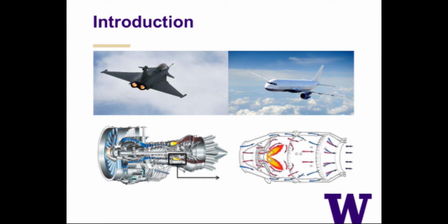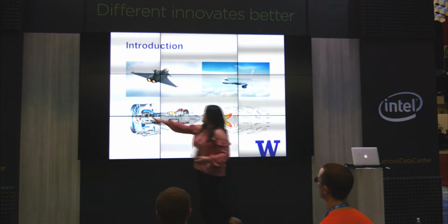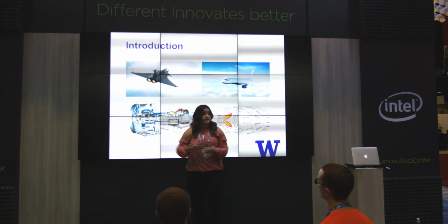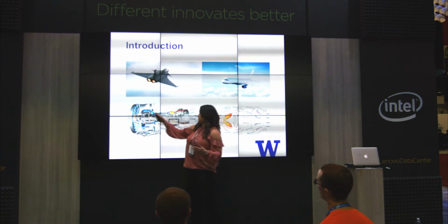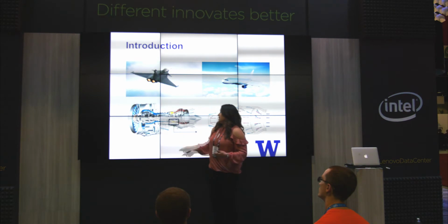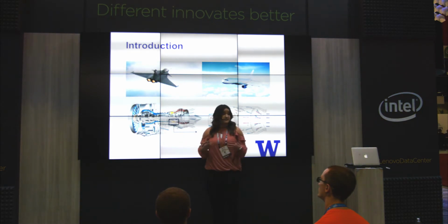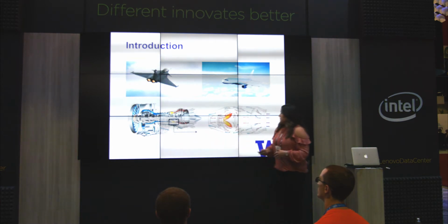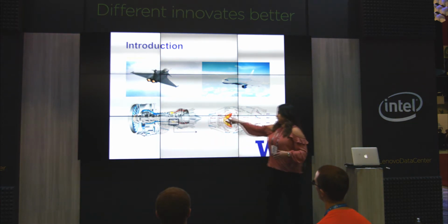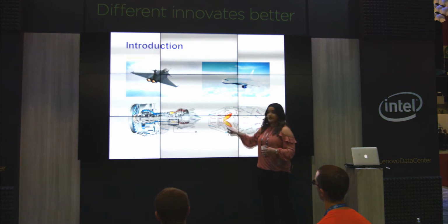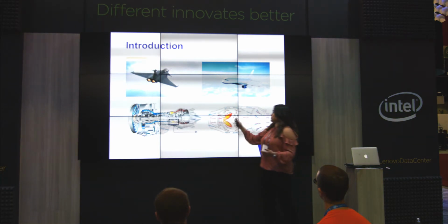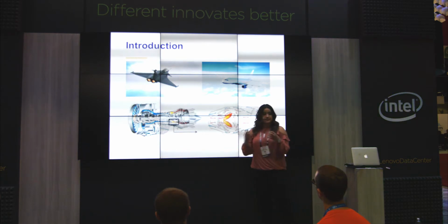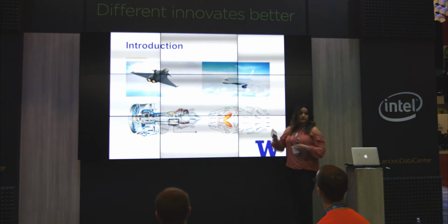As you know, when we fly an airplane, we use a gas turbine to create a thrust. Air comes in, goes to the compressor, which takes its pressure really high. We send this high pressure fluid to the combustors, and the hot gas fluid has a lot of energy, goes into the turbine and creates a thrust in the airplane. If you zoom in on a combustor, you can see that the fuel and air come in the combustor. It goes through a recirculation zone where the flame is stabilized, and then it exits and goes to the turbine.